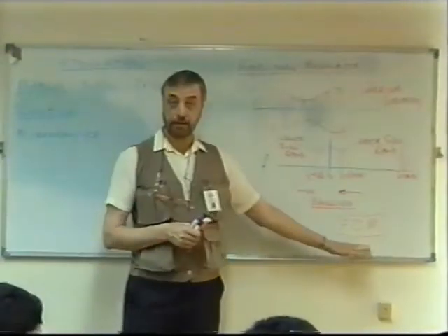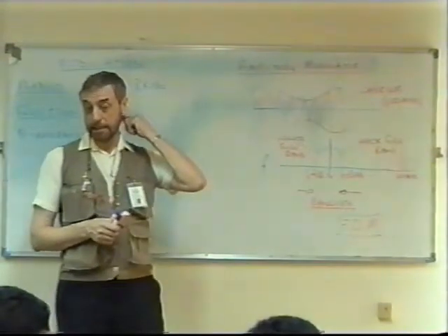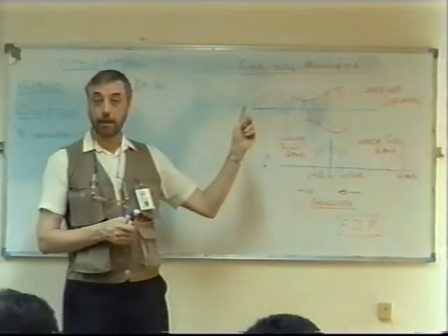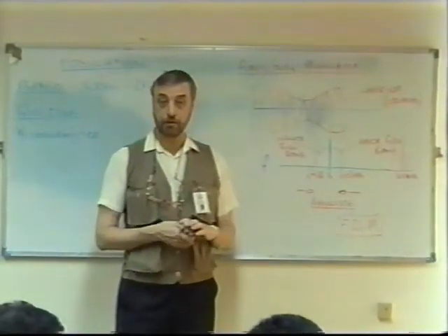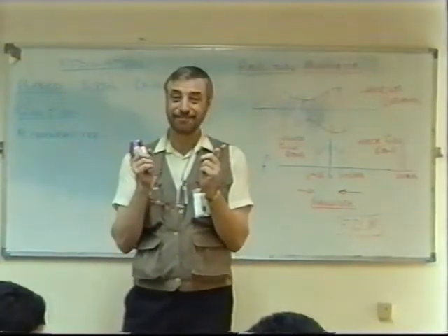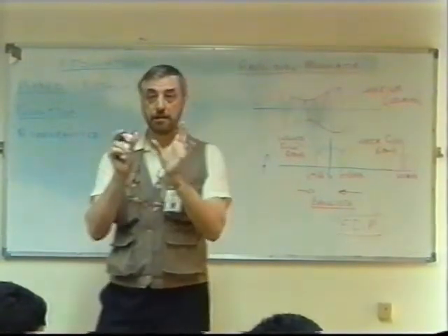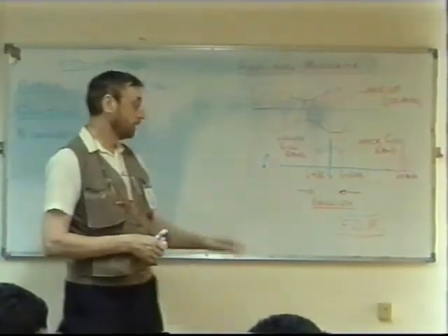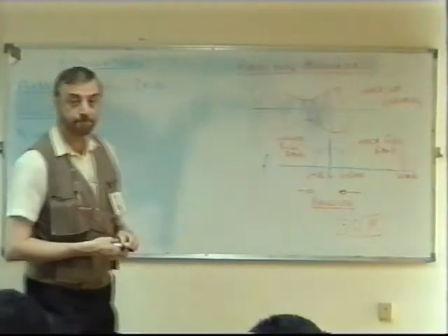Sorry, what did you say? Use this frequency division mechanism only for... No, I didn't say that. This is general. This is just an example of FDM, that's all. It doesn't necessarily mean that we have to use amplitude modulation. In a little while I'll tell you about the other types of modulation we can use. But they all have one thing in common, they all produce a band of frequencies. As long as each person transmits on a different band of frequencies, we can call that frequency division multiplexing.